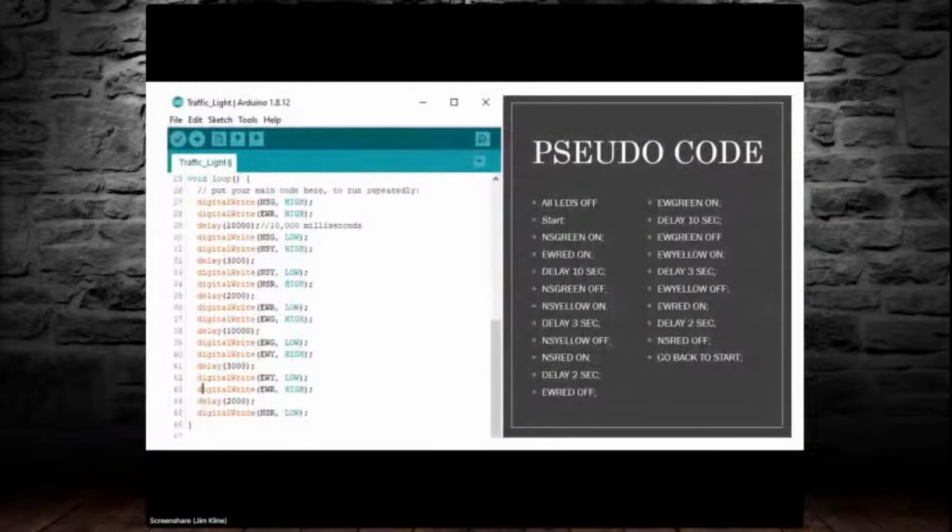We can read the state of the pin attached to the push button, but where do we put the code? We could place the code to read the button after or before each delay. However, it is highly unlikely that the pedestrian will push the button at that exact instant. There should be a way that the program continuously checks to see if the button has been pushed. Actually, there is more than one way, but we will use a basic repeating loop structure known as a for loop to perform that task.